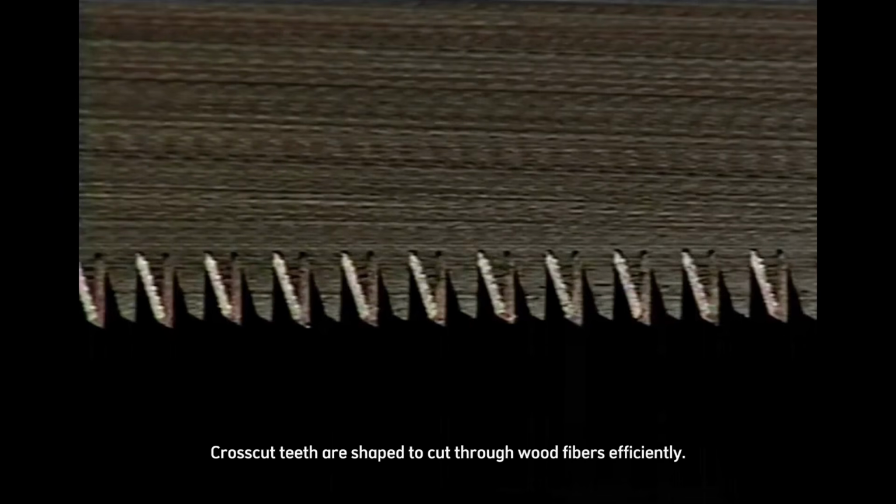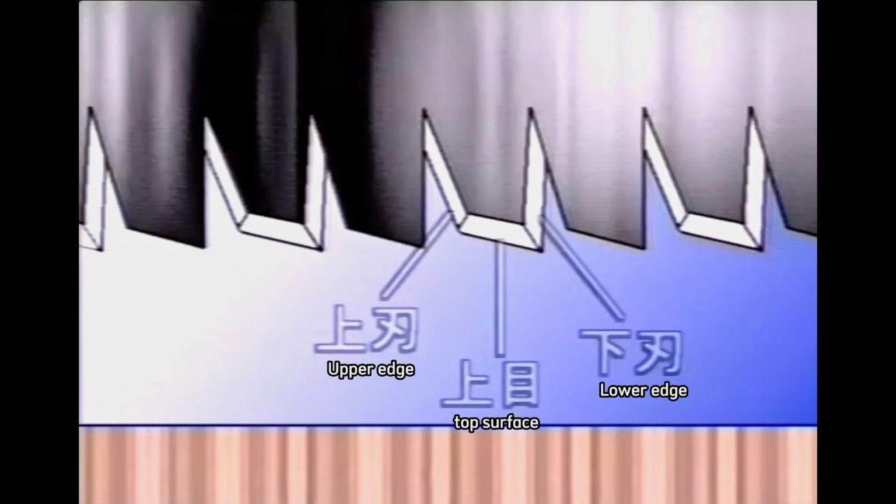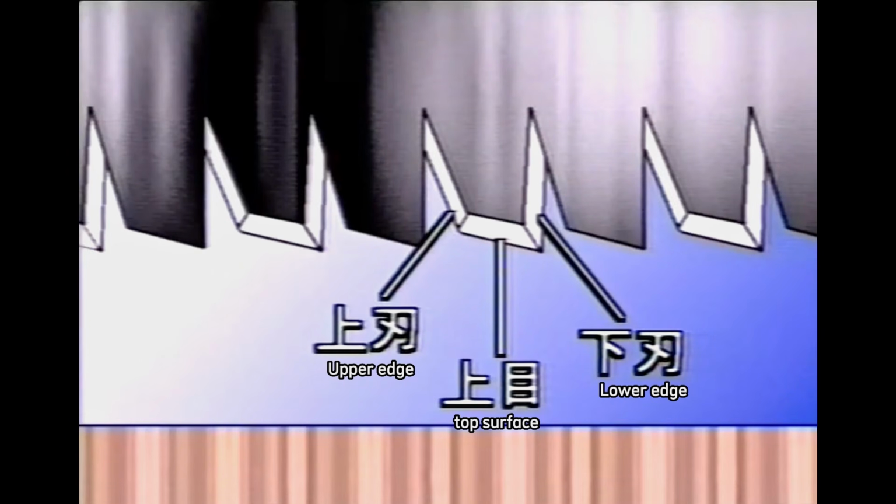Crosscut teeth are shaped to cut through wood fibers efficiently. Crosscut teeth have upper and lower edges, plus alternating side edges. The rake angle is generally set at 90 degrees, and the cutting edge angle is approximately 45 to 60 degrees.